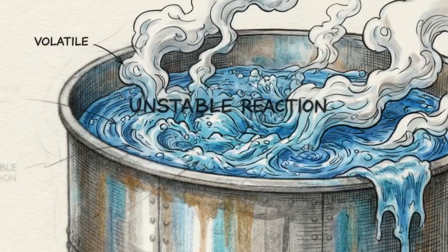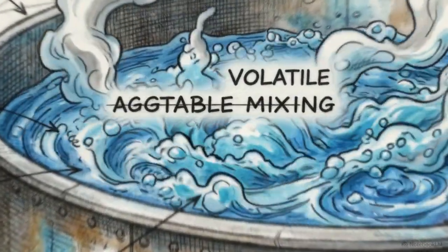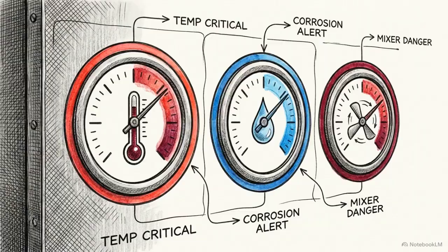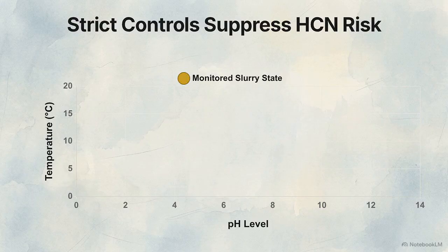While oxygen and cyanide extract the gold, combining them creates an inherently unstable chemical environment. This forces us to introduce rigid safety boundaries that wrap around the entire operation, specifically temperature, pH, and agitation. The primary threat here is volatilization. The cyanide inside the processing pulp easily reacts to form hydrocyanic acid, or HCN, a highly toxic, lethal gas. This scatterplot maps out the exact environmental controls required to suppress that reaction.